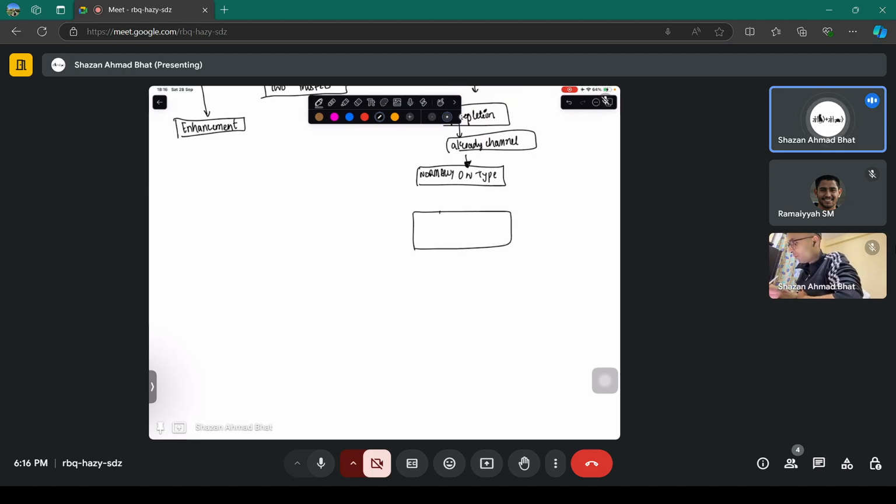Just like for example, if you have this N plus source, this N plus drain, this oxide, and this metal, then you will have electrons here already after you have fabricated it, even if you haven't applied any voltage.